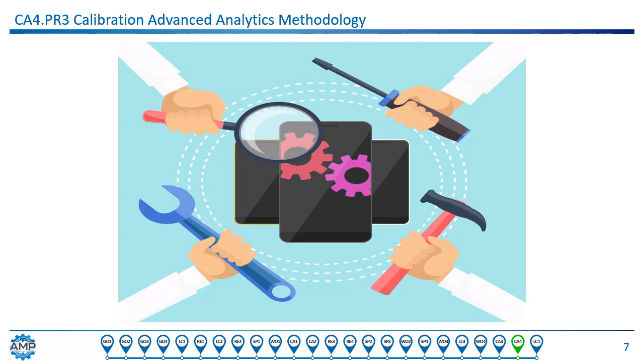The process just has to be defined in terms of data requirements, interfaces with other reliability processes, roles and responsibilities, and reportability so it is auditable and sustainable. Periodic trending reports should be created to identify poor-performing calibrated instruments. Annual review of periodic trending reports should be executed to determine if any poor performers should have a reduction in calibration interval or be replaced.